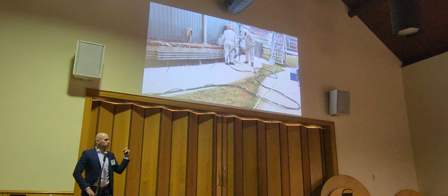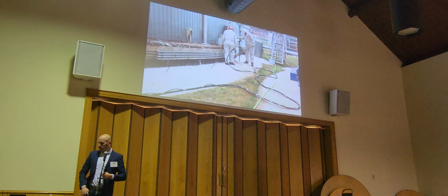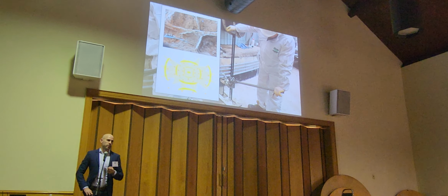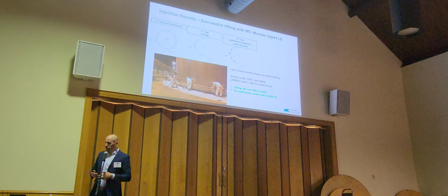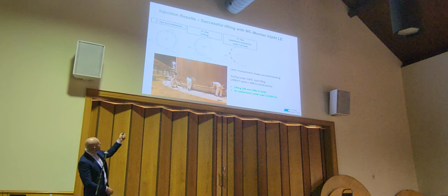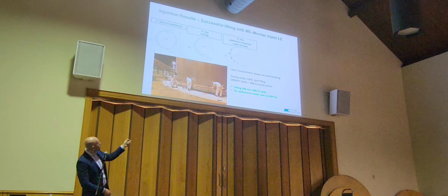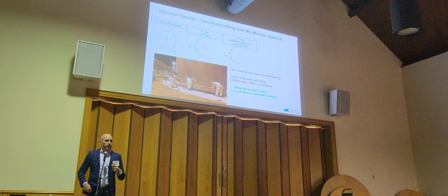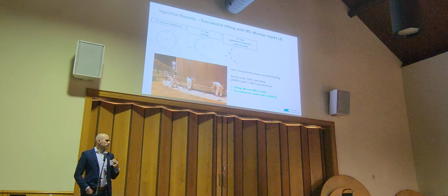If you see this project here with a complete tank, that was displacement grouting. If you see the complete project here with all its injection points in the first step, in the second step on one side, and here another step to make sure that there is no settlement, then we are talking about, let's say, 500 liters of resin.